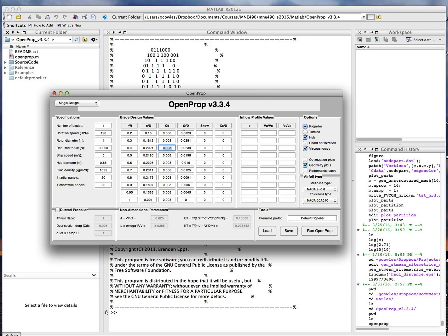And this is a thickness distribution. I'll show you the thickness profile, but basically this is the thickness relative to diameter of the section. So if you were to saw the blade off here or here, further from the hub, and measure the thickness of the section that makes up the blade at that point, you would see this. And you can see it's getting thinner. In fact, it rapidly thins and then it sort of stays the same here.